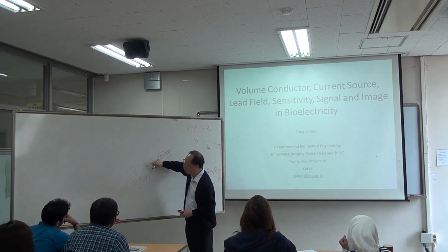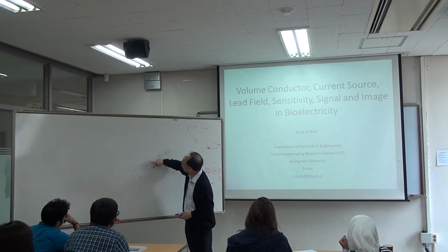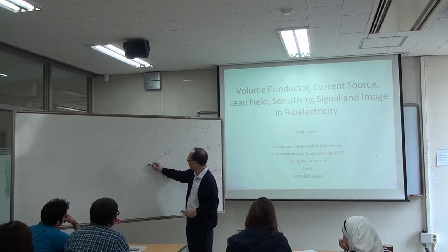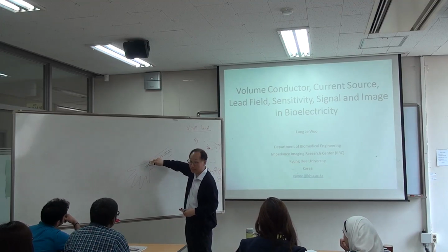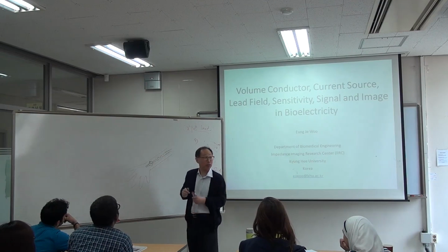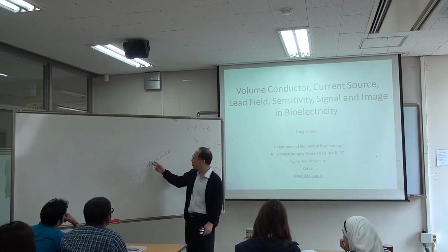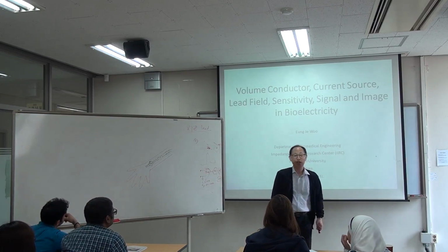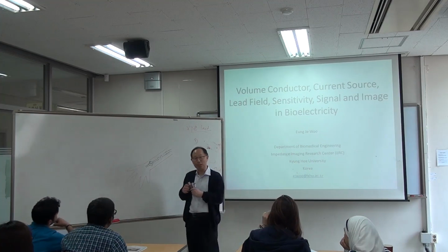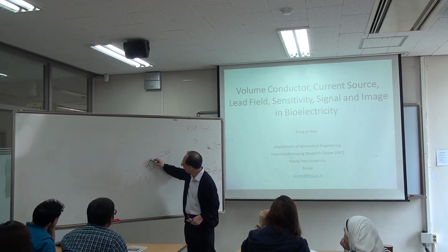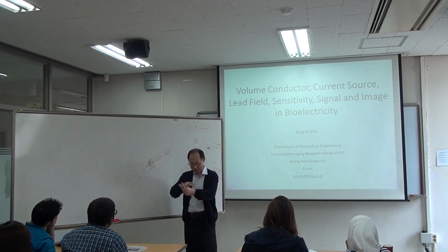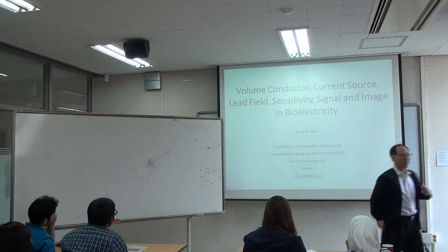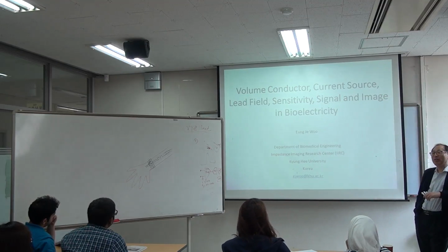The impedance around this segment is going to be large in this case, and when blood is appearing here, the impedance around this segment is going to be reduced because there's going to be more conductive fluid in that region. So we want to measure the impedance of this body segment, right? This body segment. What should be the electrode configuration?